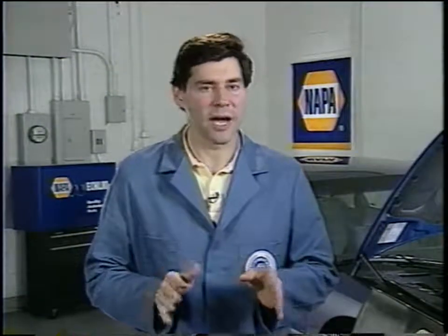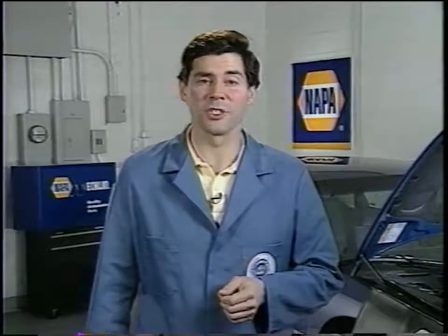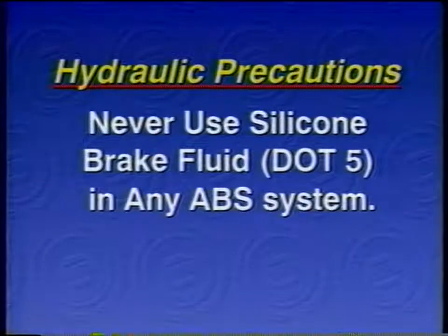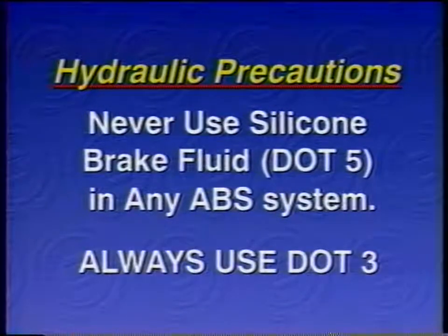Failure to follow these hydraulic precautions could result in injury. On all integrated ABS systems, you must depressurize the accumulator by turning the ignition system off and depressing the brake pedal 40 firm applications. And never use any silicone brake fluid, DOT 5 fluid, in any ABS systems. Always use DOT 3 fluid.